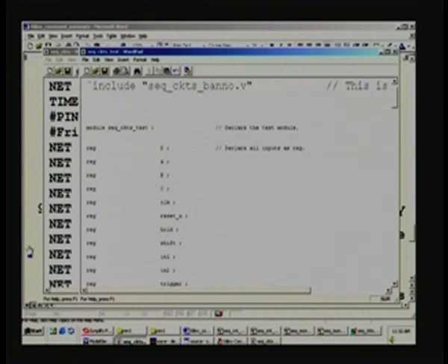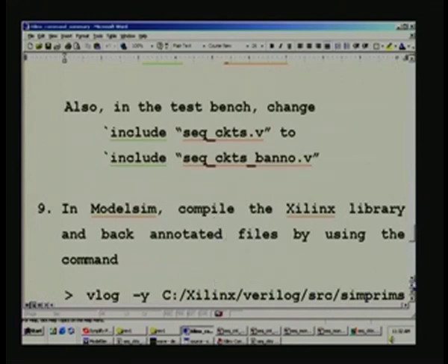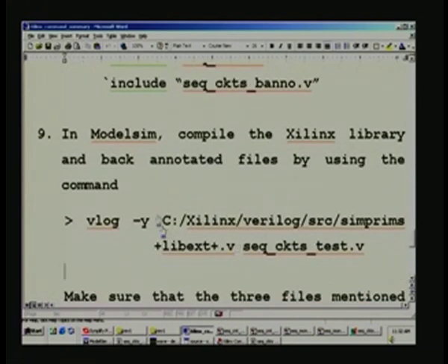So now next step, let us see, we will just follow this is to compile. Before we compile, we will have to open the ModelSim. The primary goal is to back annotate and get a back annotated file, and this is very much akin to the source file, your design file, and this file will have to be taken into the ModelSim and simulated, and make sure that after back annotation the gate delays take effect. That is the primary purpose of doing this, and in order to do this one, let us open, I mean